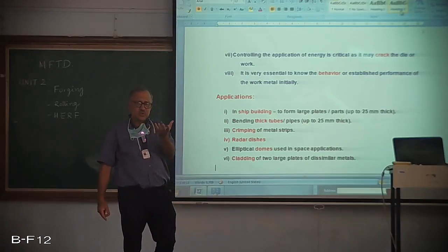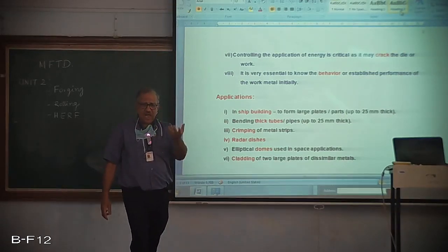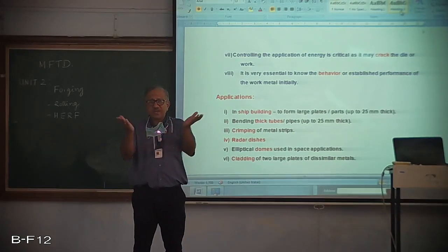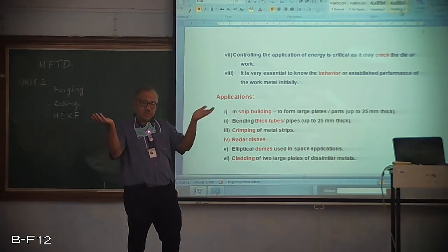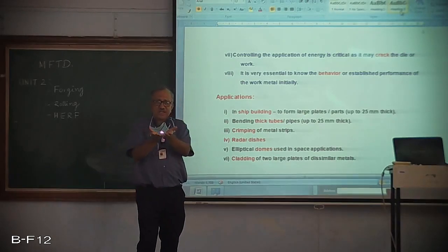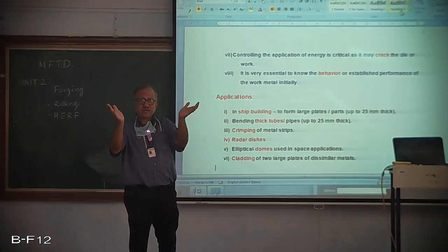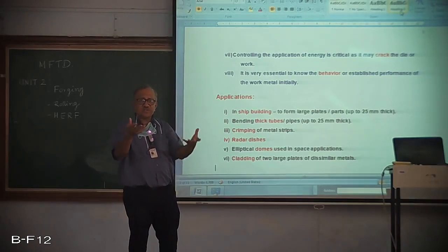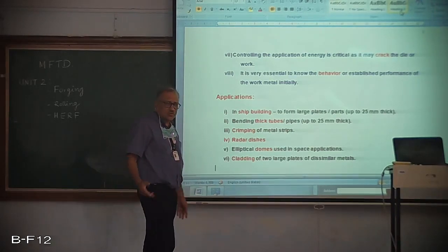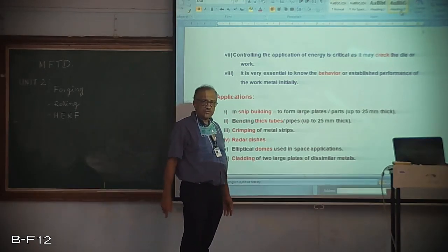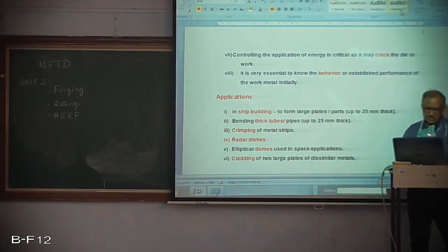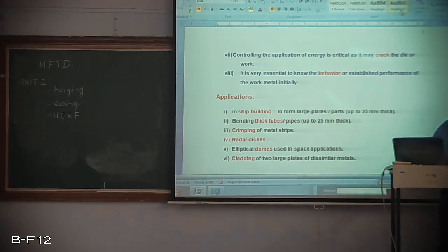Here we use the high thermal conductivity of the copper so as to minimize the wastage of heat. At the same time, we have stainless steel to contain the food, which is a superior material to withstand corrosion and other chemical attack. So one example is the cladding of stainless steel and copper.